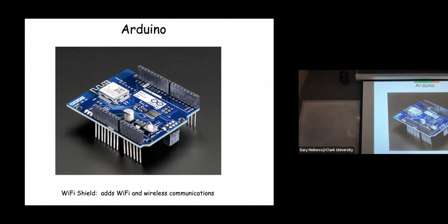And if you had an Arduino Uno revision 3, not the Arduino Wi-Fi that we're using for this class, in order for it to do Wi-Fi communications, you'd need to buy this shield and plug it into the Uno 3. And the Uno 3, along with this Wi-Fi shield, gives you most, but not all, of the features of the Arduino Uno Wi-Fi revision 2, right? This adds Wi-Fi, some Bluetooth, but it doesn't have the IMU. It doesn't have the, well, the new ones might have cryptography, but it doesn't give you all of the features.